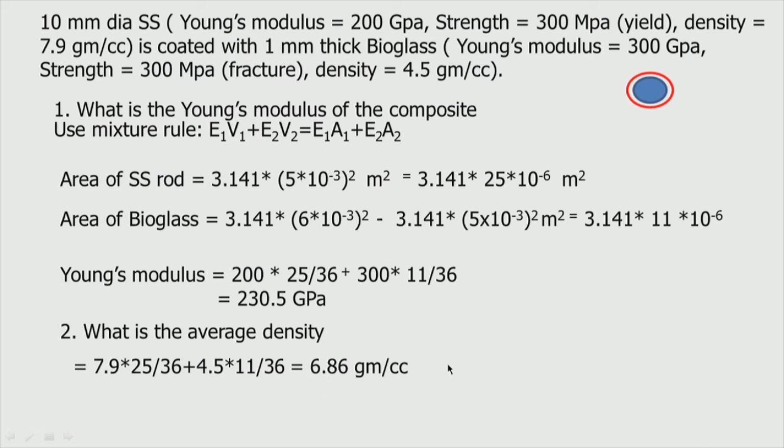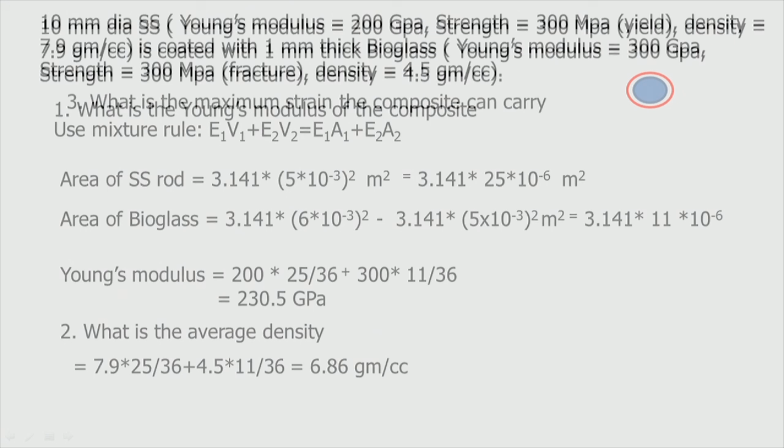Here we use the mixture rule, where both contribute based on their volume fraction or area fraction. But in a real case it might not be so, because if you remember, there is another rule called Reuss's rule we studied long time back, where the equation is slightly different. So, you may get a slightly different answer if you use that particular rule. Okay, let us proceed with the problem.